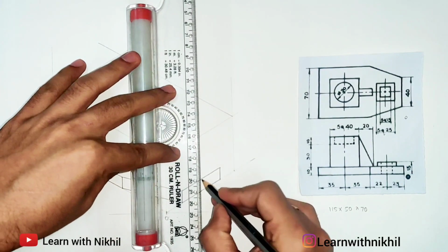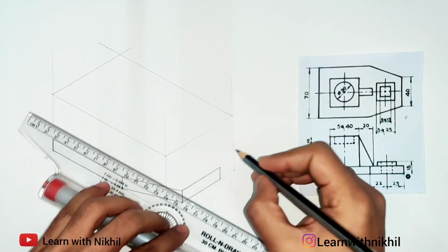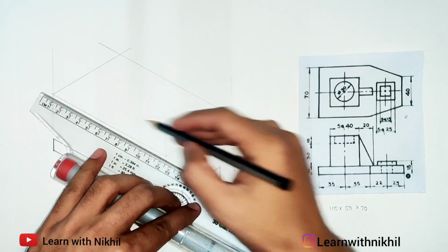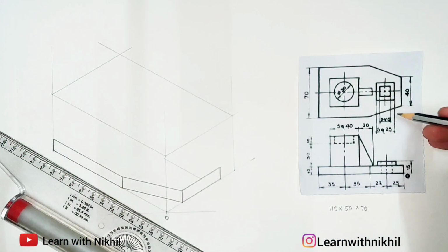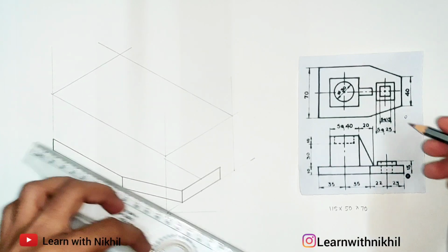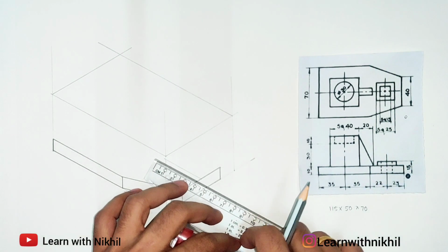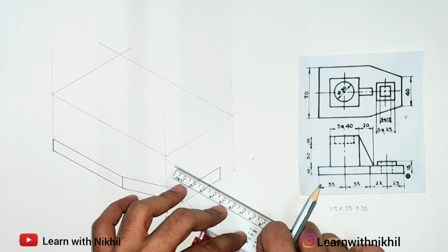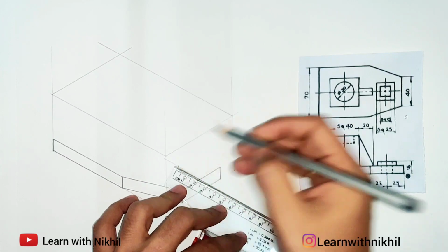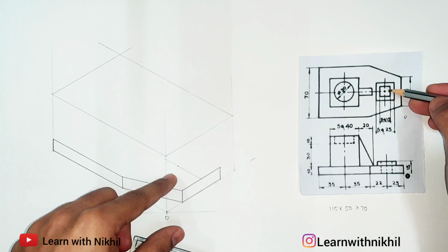So here you have already marked the point, center point. I've projected it upward, then projecting it on this line, as the square and the circle is placed at the center. So this is the center line we have drawn. Now starting with the square, it is behind at a distance of 23 millimeter. So from this point 23 millimeter behind, I'll mark a point. That will be the center point of the square. So you will draw the square.